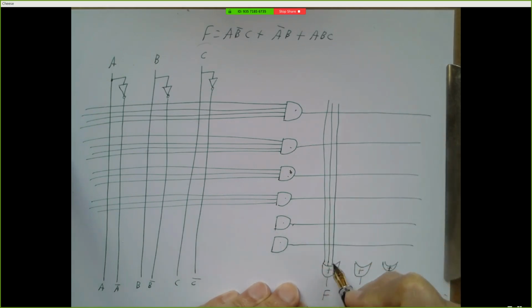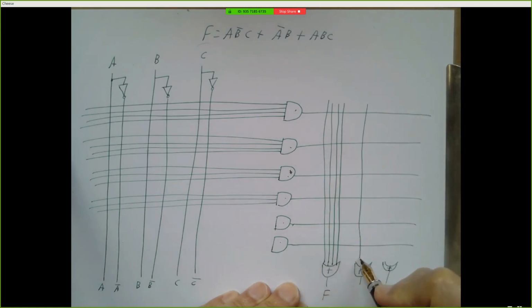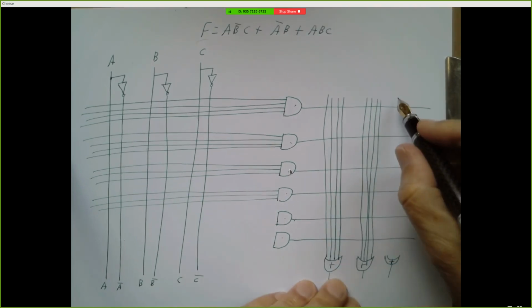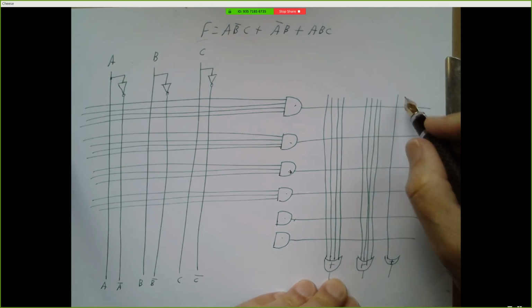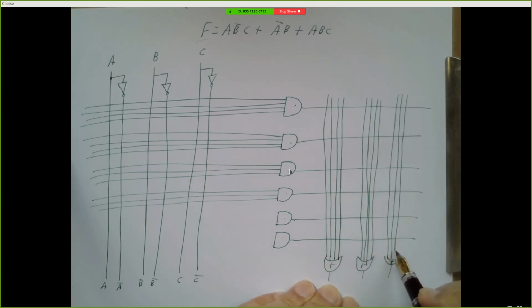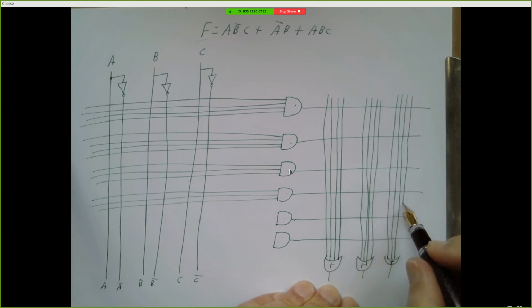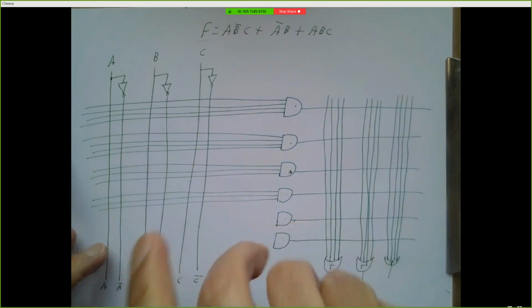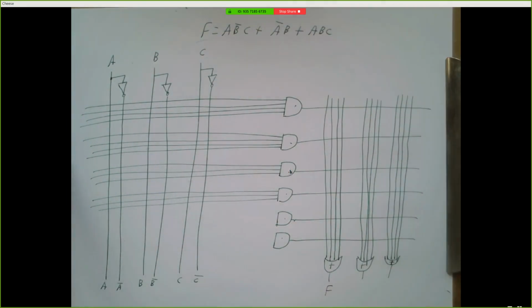Now, when you draw a schematic on a 2-dimensional piece of paper, it's hard not to have wires cross each other. It's inevitable, right? Because sometimes that's just how the geometry works out. So when wires cross each other, we don't assume that they're connected. What we do is, if we have wires crossing and we want to indicate that there's a connection, we draw a little circle where they cross. So right now there's no connection between this wire and that wire. They're just wires that happen to be crossing each other, just like on a protoboard, two wires might overlap, but they're not connected, right?